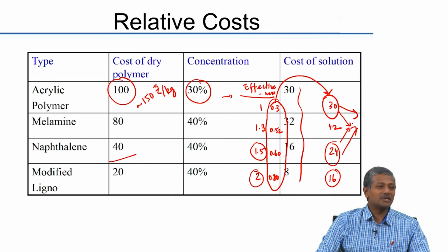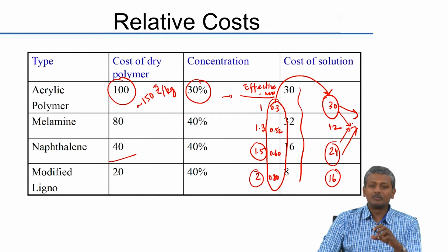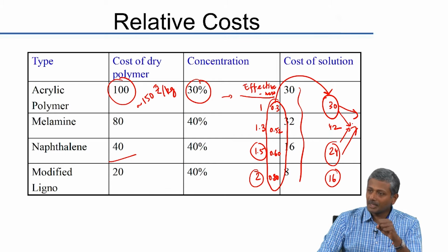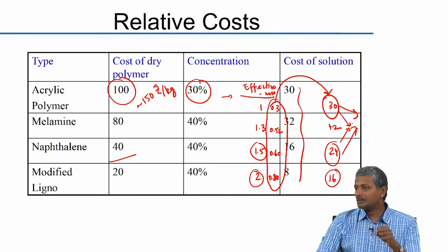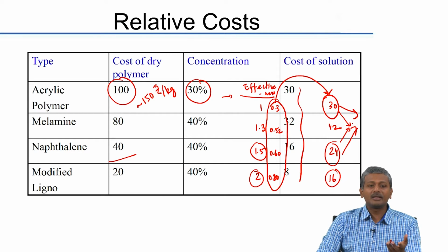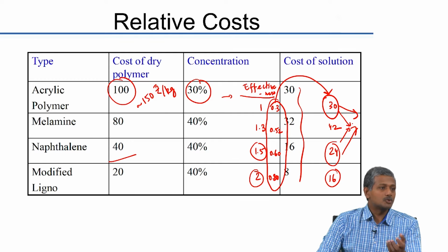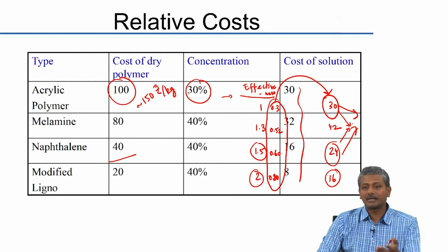So, that way what I am trying to say is the more stringent the mixture design gets, the more economically feasible will be the use of specialized additives like the polycarboxylic ethers or acrylic copolymers.